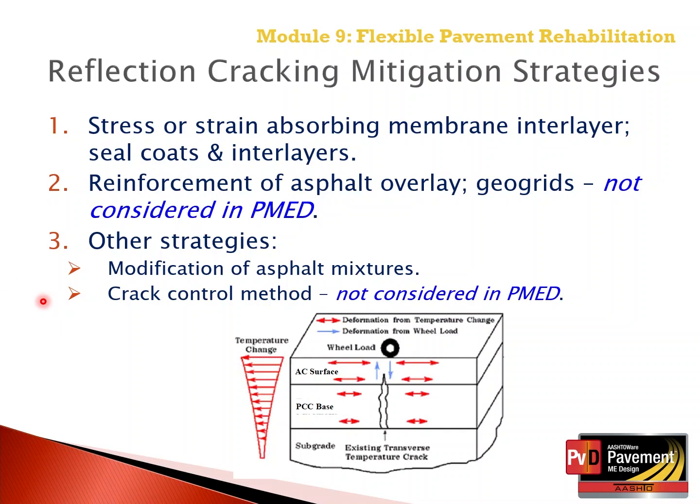The crack control method is also not considered in the Pavement ME design software, but we're going to go through a slide shortly because that mitigation method of crack control, in other words, sawing and sealing above the transverse cracks or transverse joints in a concrete pavement, has been considered successful.